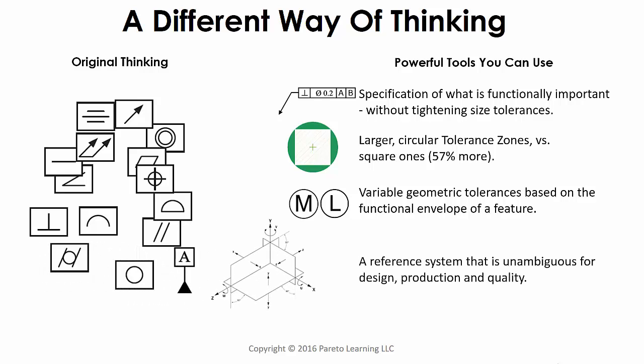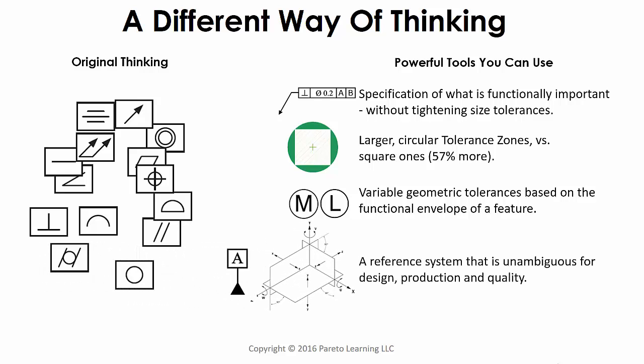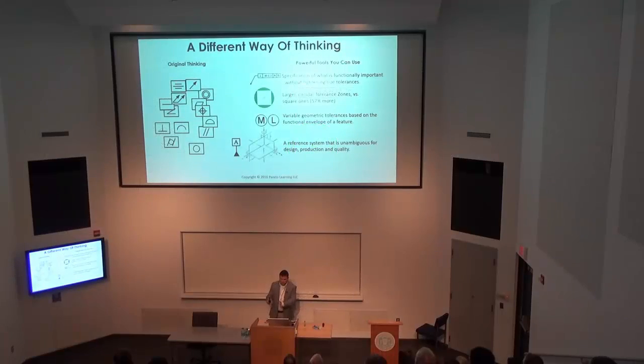And finally, it gave me a core reference system that is unambiguous for design, production, and quality. It carries along. Everyone can understand the core datum reference frame as it moves along if they understand GD&T, especially when you're giving it to a supplier. You have the same datum reference frame if you use the same datum set.